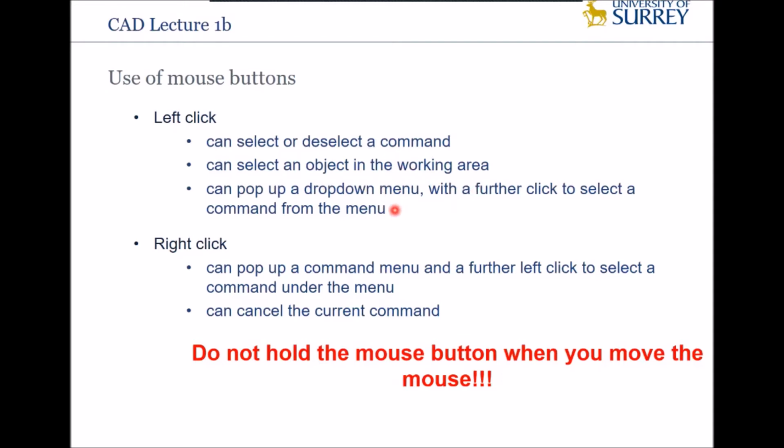Unlike other software such as Microsoft Word, it doesn't use the right click often, but you need to know how to use the right click so you can carry out the modeling using Solid Edge. Right click can pop up a command menu, and a further left click will select the command.